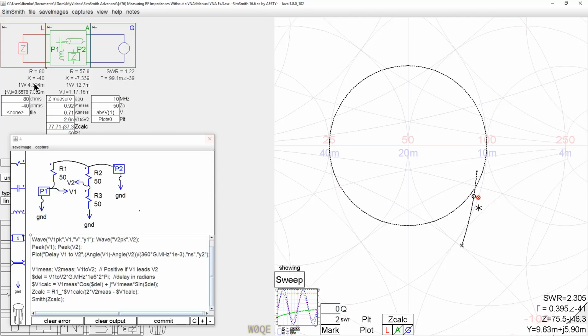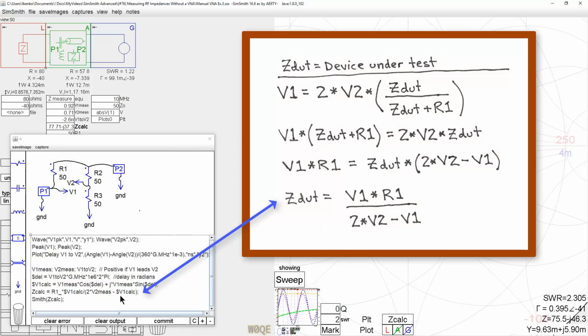This is not the only circuit you can use. You can put a directional coupler in here. I've used directional couplers before. They get voltage outputs. You measure the voltage outputs and you measure the phase. And based on the coupling coefficient, you change the gain here. But this is a pretty simple thing to do. And all I did here to get this formula was to change the order of calculation, and that's shown up here. And this is a fairly simple thing to do.